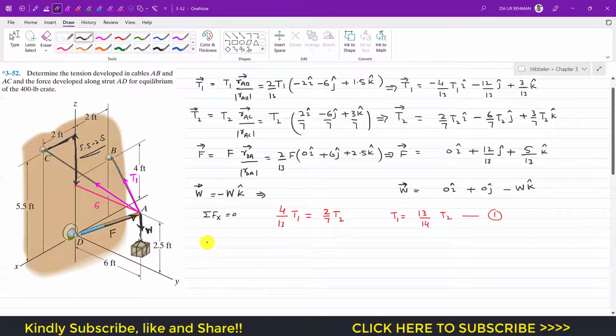Now if we apply the summation of forces along the y-axis equals 0, we have to add up all the j components. So that is minus 12 divided by 13 T1, remember this is T1, minus 6 divided by 7 T2. Since we have replaced this T1 in terms of T2, we need to write this T1 in terms of T2 as well.